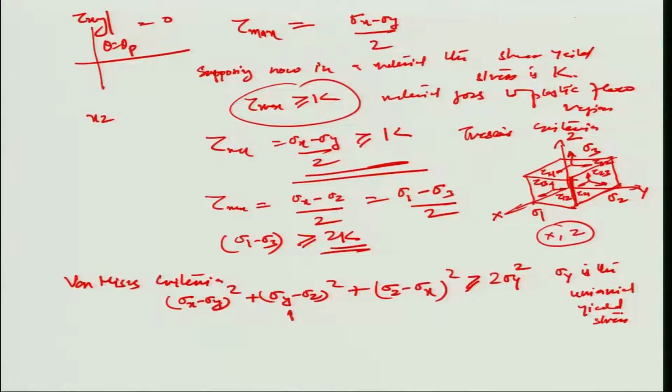And so if we wanted to follow the same principle here, where let us say generally in a forming process the sigma x becomes sigma 1, and let us say this is equal to some value k corresponding to which the material will come in plastic flow, or you can say the constant material property, flow property, which is also the yield property of the material.